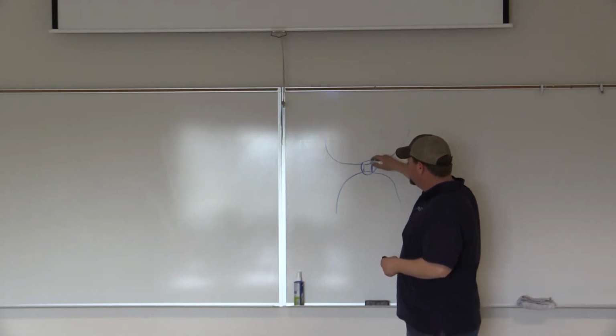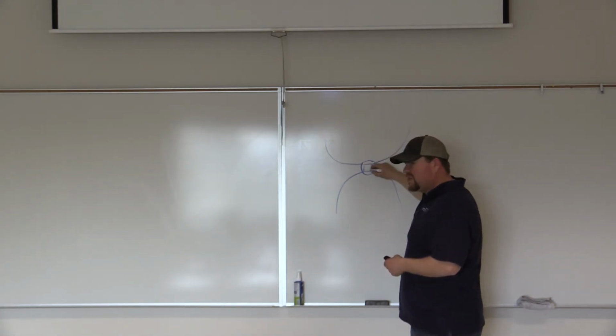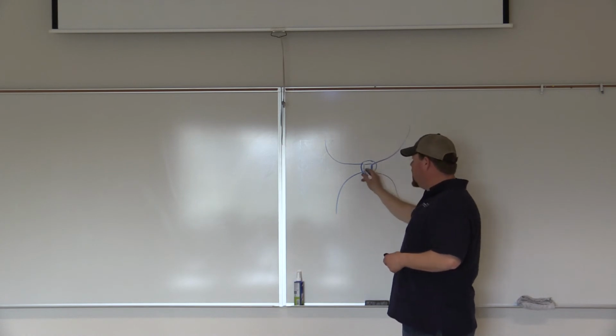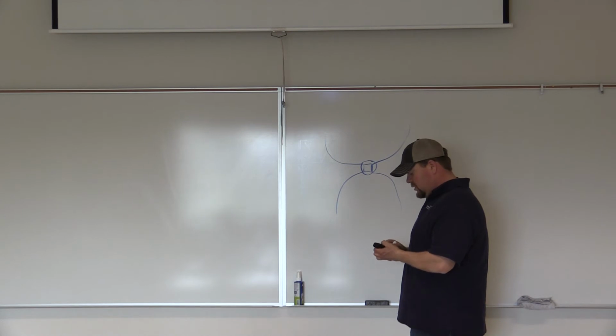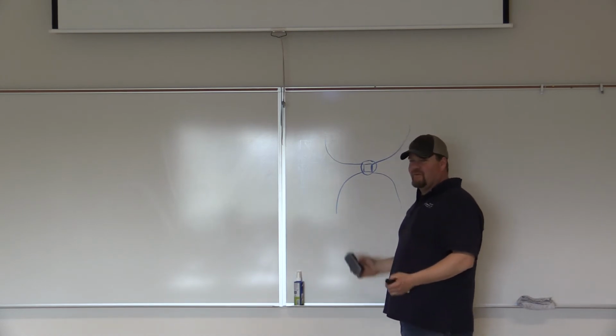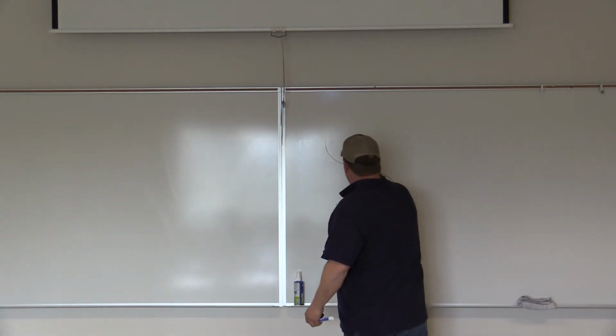Both joints, you come from both sides, so you weld this one with TIG, and then you come back around this side, and you just fill it in and bring everything to the surface at the same time. Okay? Kind of cheating in my book, but, you know.